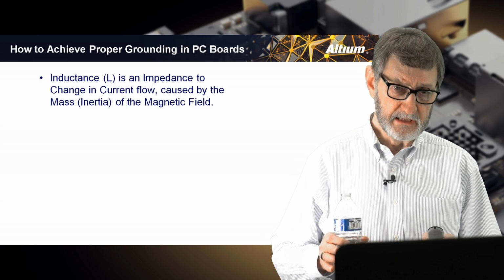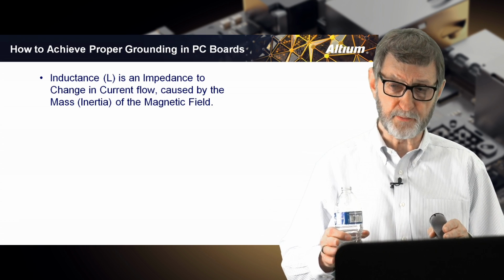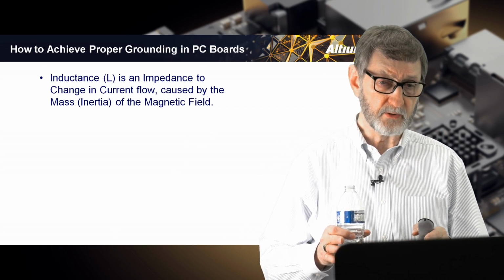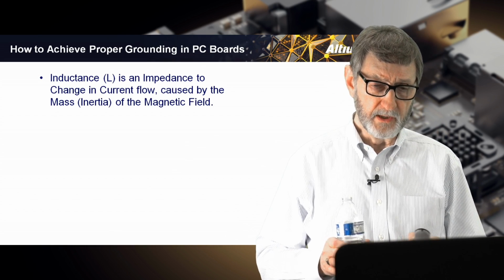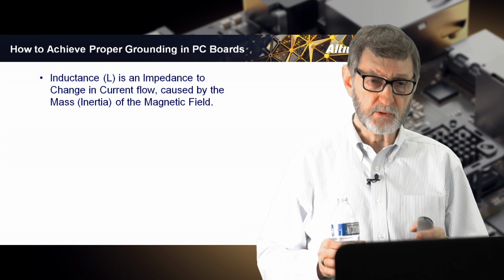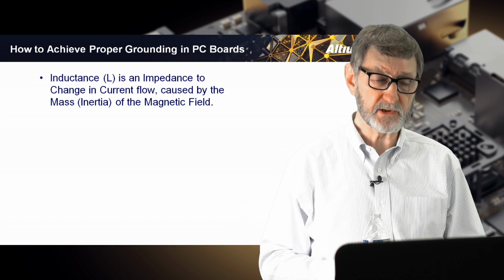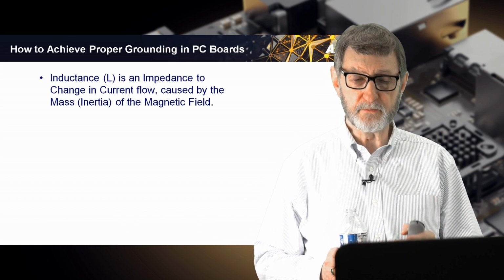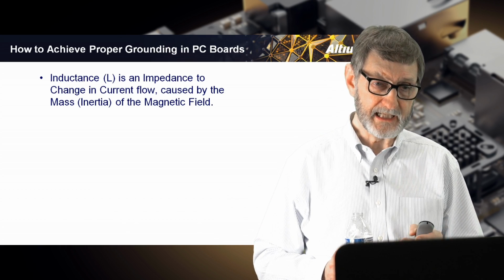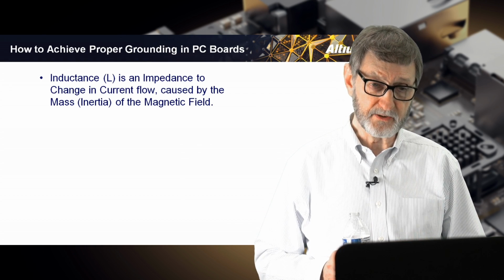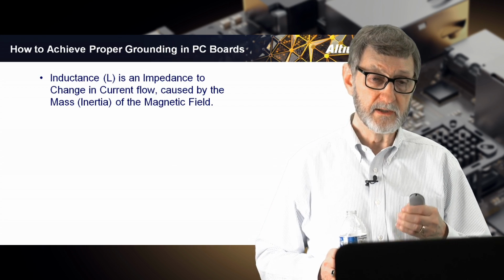If we move those 2 traces that are separated by 75 millimeters down to 1/4 of a millimeter or 1/8 of a millimeter, where they're 5, 10 mils apart, we're going to reduce the inductance by several times to a much lower level. Why? Because we will be containing the magnetic field. It's all about the space, as Dan Beeker would say. It's all about the space.